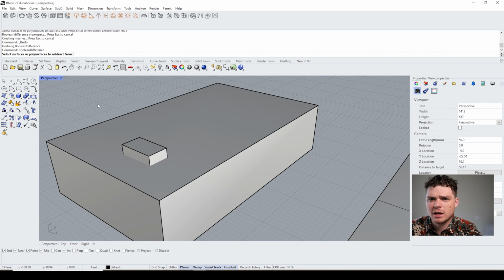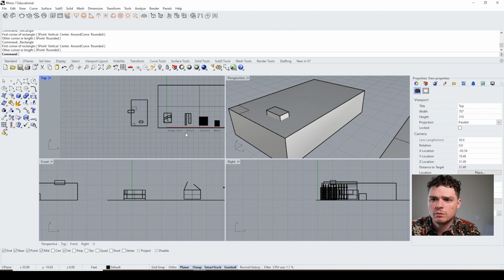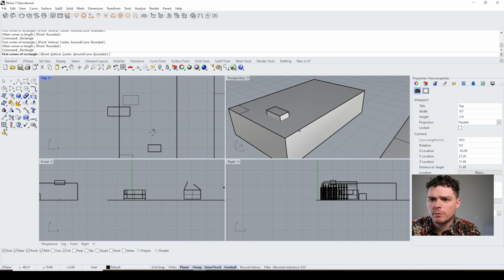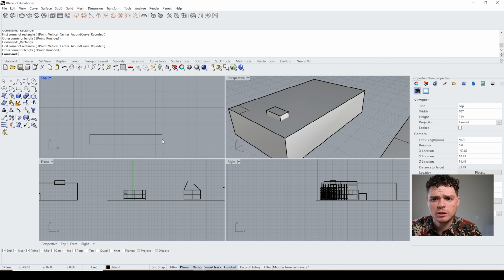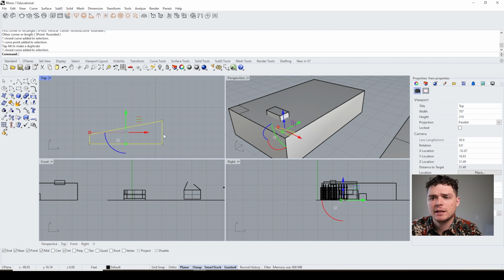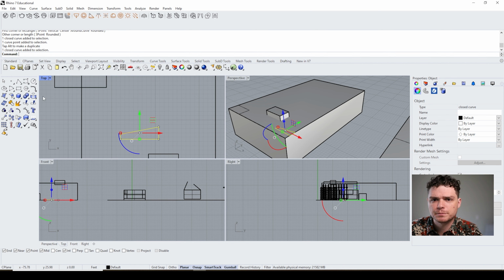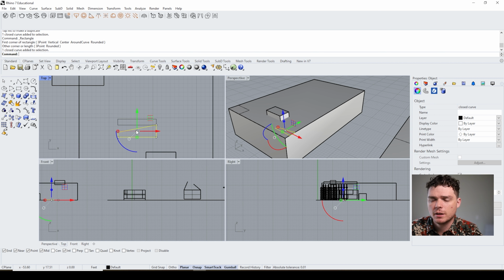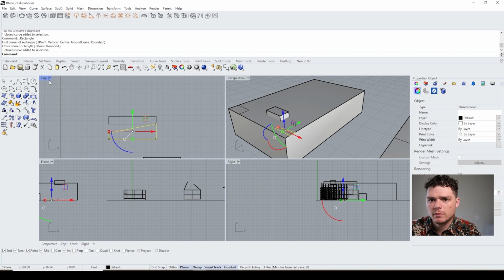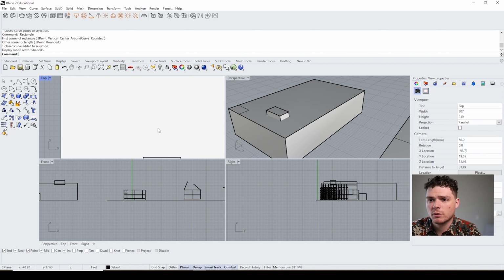Another way that you can subtract geometry is using the trim function. I typically use the trim function more so when I have line work. So let's say I drew some line work in 2D here. And maybe I have something a little bit more intricate, or I have a lot of things that I've modeled in line work, and then I want to translate that into cutting an object. So let's say even if I had a series of stairs or something. So in the trim, you have to make sure that shaded is on in order for it to work.